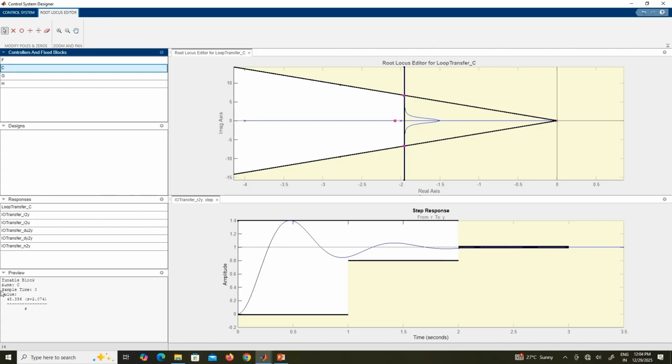If you look at G, you see this is the G that you get. Okay. Looks like we have solved the problem, right? I mean, I have introduced a 0 and I have introduced an integrator also. Basically, I have introduced a pole at the origin also, and looks like we have solved the problem. Theoretically, yes, but there is an issue with this.